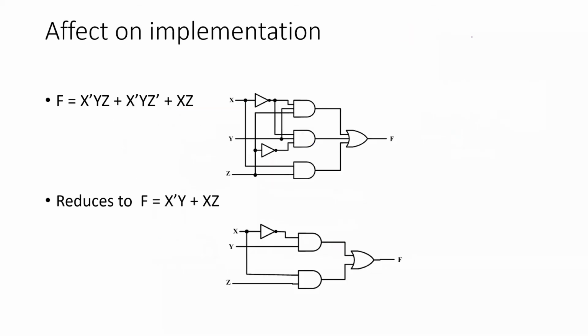So then suppose you implement this using this logic expression, you will find out total number of gates required are 1, 2, 3, 4, 5, and 6. When minimized, total number of gates required are 4. So you are saving 2 logic gates in one module. And when you talk about a system, you are having millions of modules.